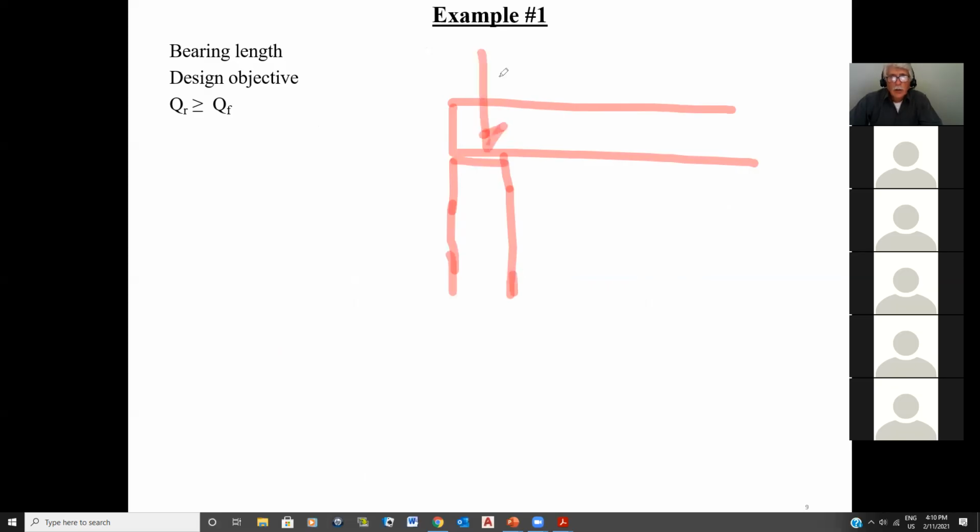And QR is a force perpendicular to the grain, okay? So that's QR. And therefore, if I look at this thing, what's the force I have perpendicular to the grain right now? It's my VF force, okay? And that's what you have to always keep in mind. Always say, what are the forces that are perpendicular to grain? In this case here, there's only the VF force, therefore it's only VF.